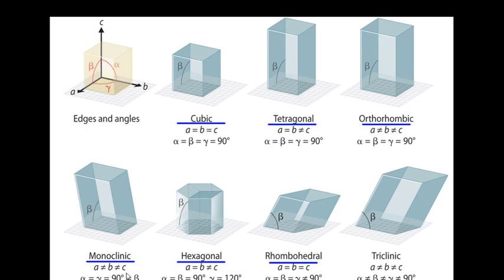The orthorhombic to monoclinic is also similar to squeezing, but where beta gets distorted, over here gamma is going to be distorted. And the triclinic, where all are mismatching, right? That is the case where you squeeze the orthorhombic such that alpha, beta and gamma are all disturbed. That means none of them are 90, none of them are equal, and that is what triclinic means.